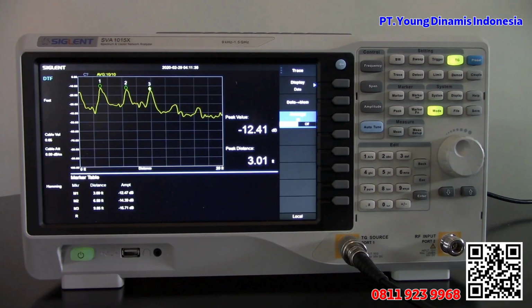I have had some customers report that they've had lightning suppression elements on their cable start to wear through the dielectric, and they can see that using the distance to fault feature. So again, they can check out where that exact break is or where the problem is before they even get up on a ladder or climb the tower.